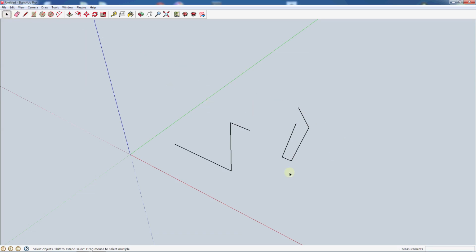Now jumping back to the select tool, here we can see by default we can select an individual object just by clicking on that. And right now, since these are all separate entities, I'm selecting one line at a time. If I want to select multiple items, I can hold down the shift key, and you see it has the plus and minus. So as long as I'm clicking on unselected items, it'll select them and add them to our selection. But if I go, well, I really didn't mean to select this line, I can click on it again and it'll unselect it. So holding shift allows you to do that. You'll notice that control will only allow you to add, so if I click on it again, it's not going to unselect it. If I hold control shift, it'll only let me subtract.